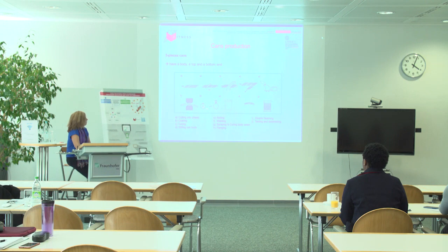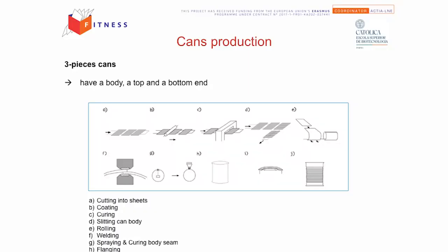So this is where it is applied here, and then with the cylinder produced, we start to prepare the can to receive the top and the bottom end. Okay, so we do some double seaming. We will see what this is, and then we may need to produce some fixtures on the body that we will discuss a little later.